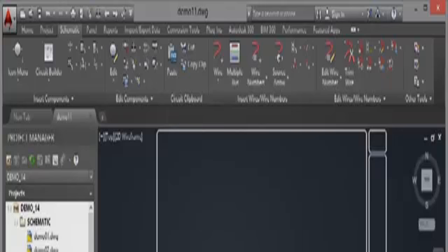I've got three-phase there with 1/2 inch spacing on the vertical wires of the ladder. The spacing of the actual connectors there is actually 3/4 inch. Can you see that? 0.75. Now the first reference that's coming in is 811, based on the sequential tagging that's going on in the project database behind the drawing. I'm going to change that there to 1000. Now the indexing is coming in at 1, so that means it will have consecutive numbers, so it'll be 1001, 1002 and so on. If I click on OK now, it says specify start position of first rung.